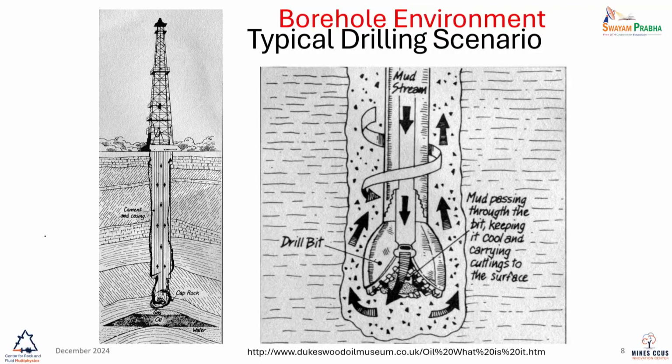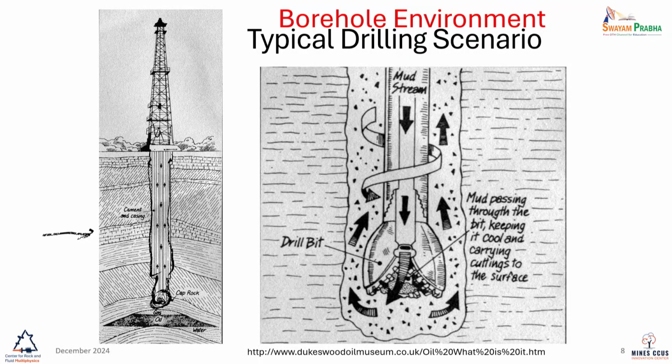For example, over here, this one here. So the shades mean something. This one is a carbonate formation, right? We know that there is carbonate in the area, but we don't know whether we will encounter it here. It could be pinched out, it could be broken up. We don't know if it's continuous. In that case, we will bring corers that allow us to drill through hard rock, but we don't know whether we'll need it or not. So that's the part which, yes, you do have to have some idea of the geology. Without any idea, going out there is foolhardy. You don't want to do that. Oftentimes, we do know what geology to expect. Yeah, sure.